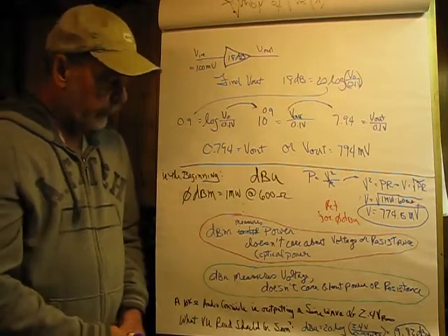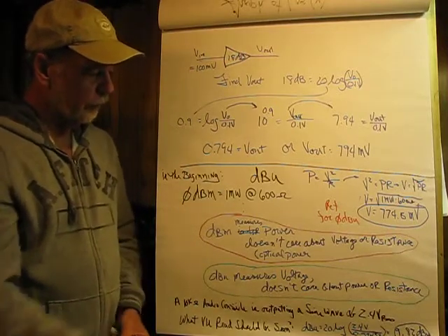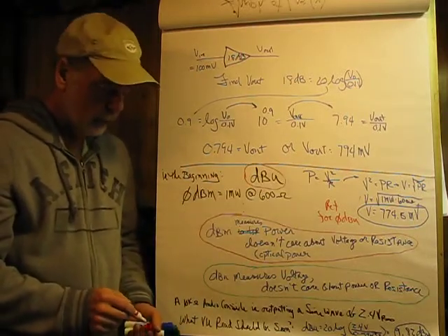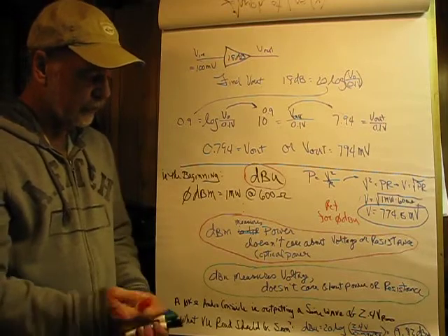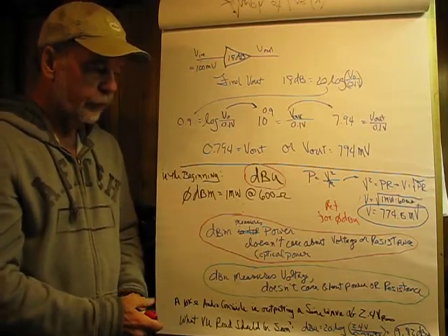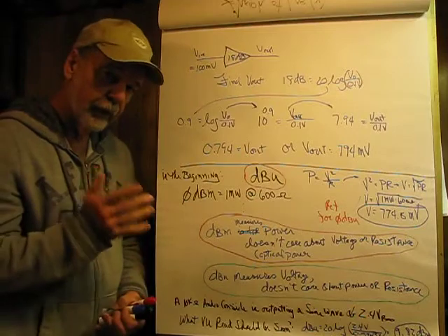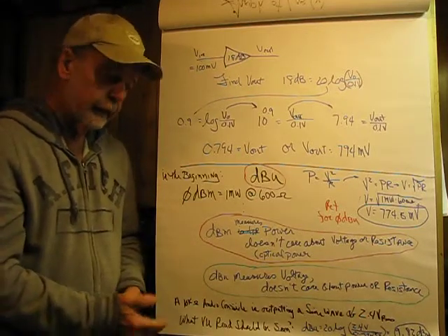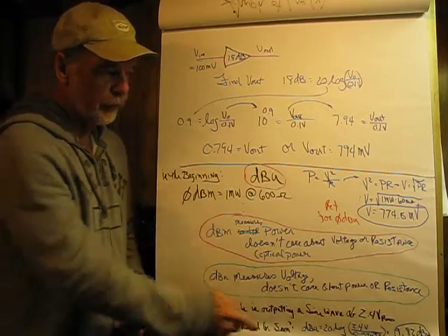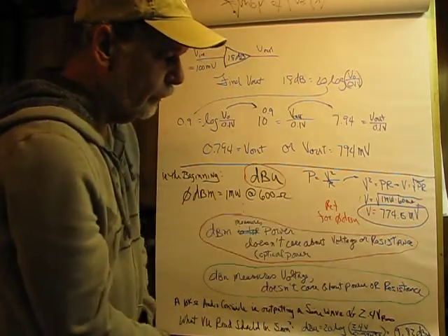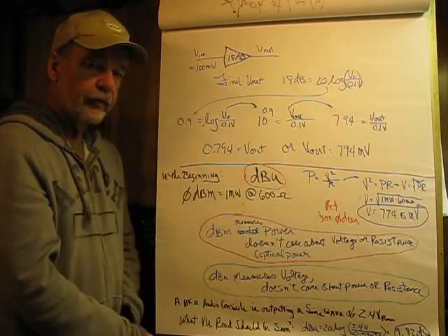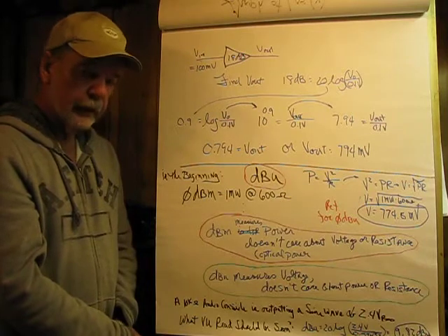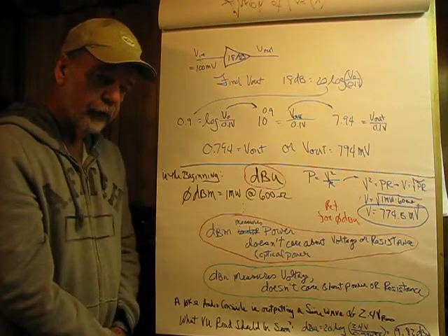Last example here, and while we're on decibels, is dBu, and this is used extensively in audio. I wanted to bring it up and discuss it for a minute. There's no changes excepting for the reference value. As dBm uses 1 milliwatt, we're going to have a reference value for dBu of 774.5 millivolts RMS. This is what the meters in audio consoles are measuring, levels in dBu.